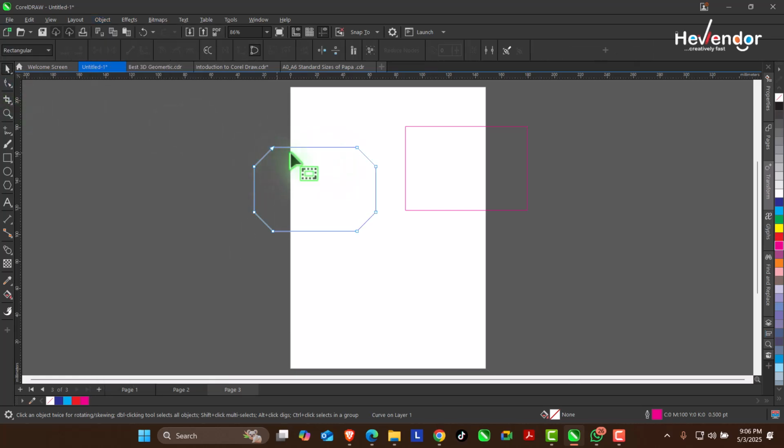Okay, so with your shape tool, you can see now this is free. When you double click on the line, you can add more nodes. See the properties of the node. You can select a line and convert it to a curve. See, you start editing and adjusting the node.